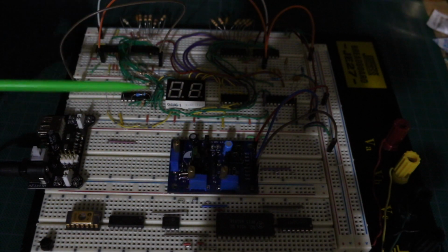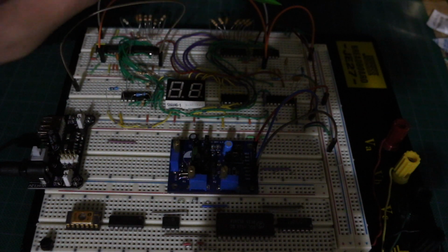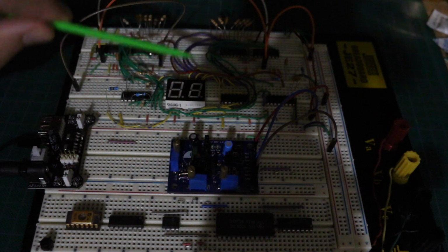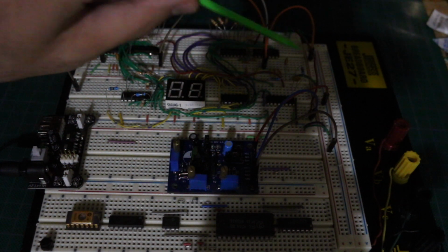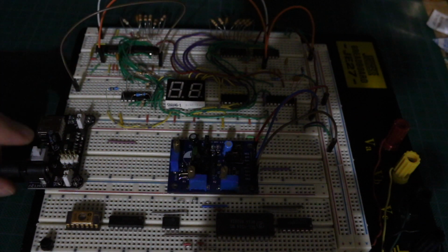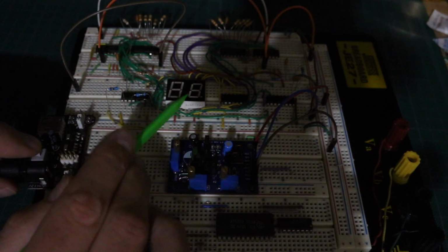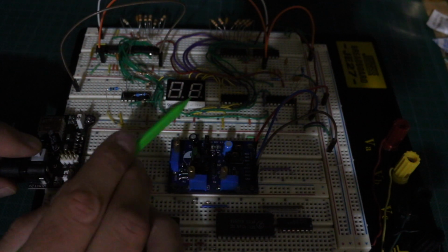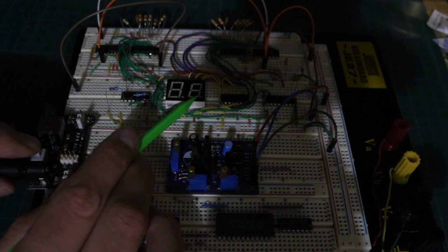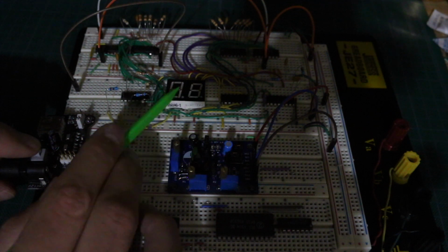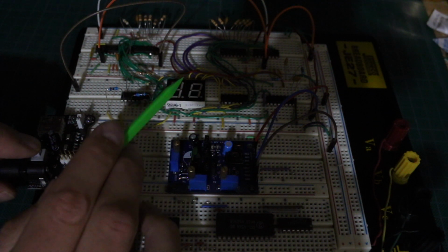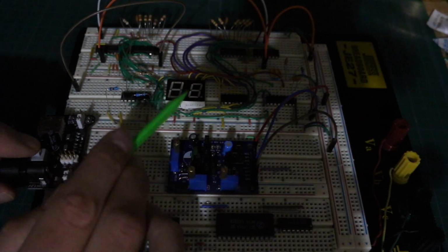So I'll dim the lights and show some of the functionality of this circuit. Right now the circuit is powered off, and the reset input that controls whether we do a power on reset or just let the circuit power naturally is tied low, so the circuit will do its own thing. When I power up, both digits start blank, but then quickly the ones digit will go to 8 and then 9, and then the tens will go 8 and 9 and then kick into 0, 0.